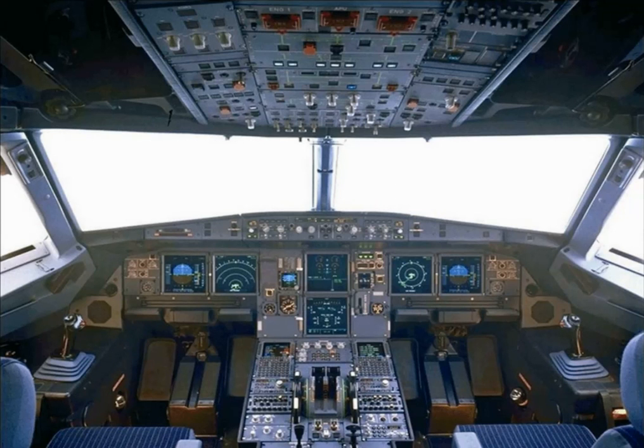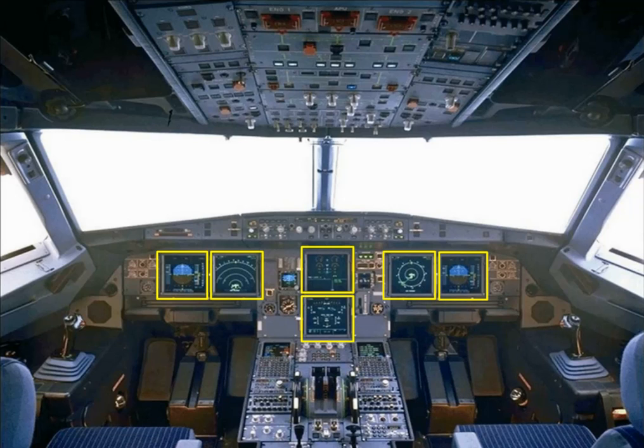In comparison to old technology aircraft, the flight deck on the A320 is designed to be a comfortable, non-cluttered work environment. By using modern electronic display units, the presentation of information to the pilots has been improved. The new Electronic Instrument System, EIS, has 6 identical full-color liquid crystal display, LCD, units. The EIS is divided into 2 subsystems.